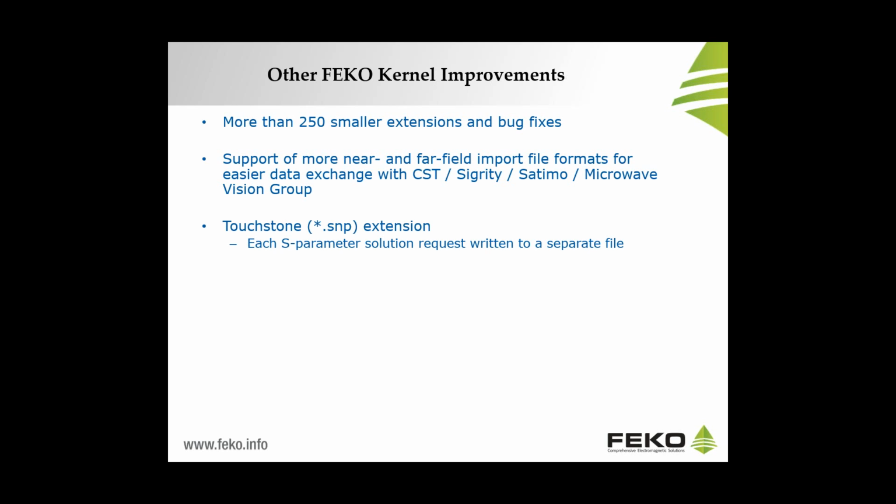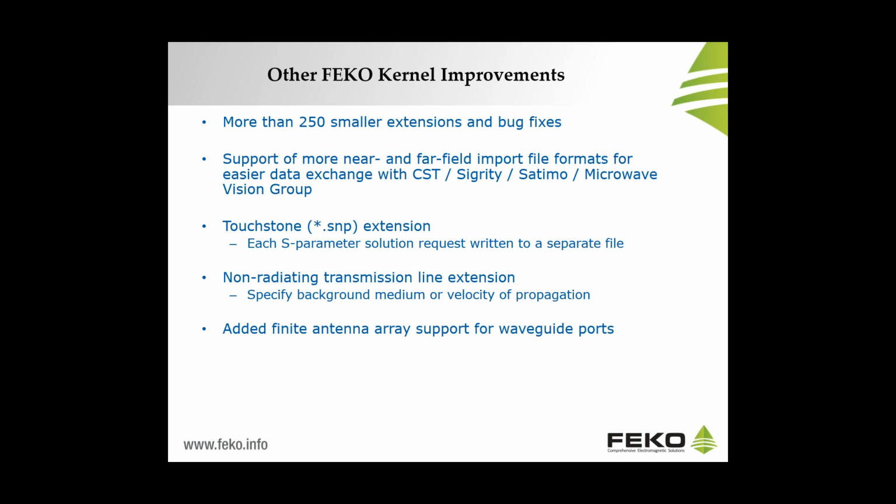You will also be able, for each S-parameter solution request, to have it written to a separate file. With non-radiating transmission lines, you will also now be able to specify the background medium or the velocity of propagation. And regarding finite arrays, we have in FEKO a very nice tool to analyze large finite arrays based on the domain Green's function method.